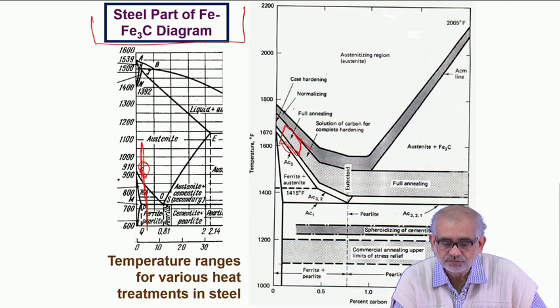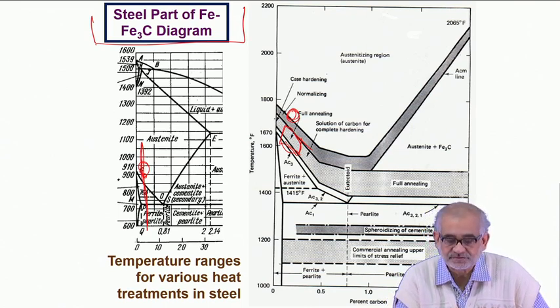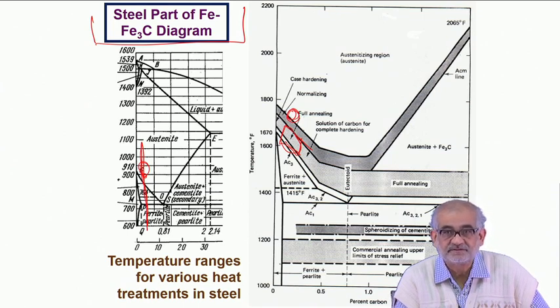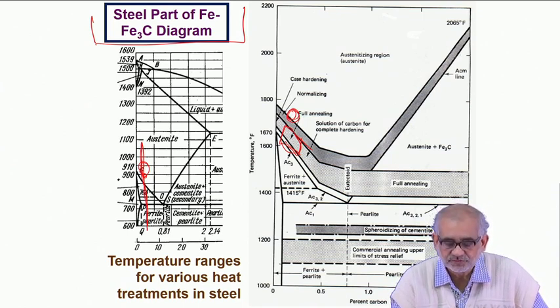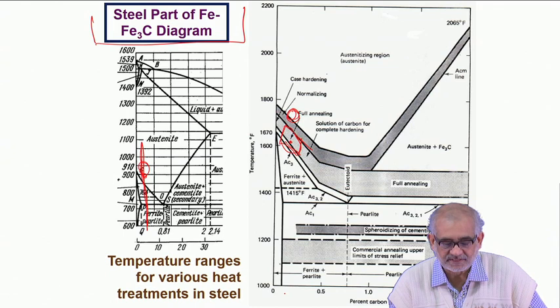We carry out the carburizing treatment at slightly higher temperature. Since we do it at fairly high temperature and the time period is longer, we generally end up getting a very coarse microstructure, and that's not very good. That's actually detrimental for mechanical properties. So when we reheat to about this temperature, and from there we have to quench fast.